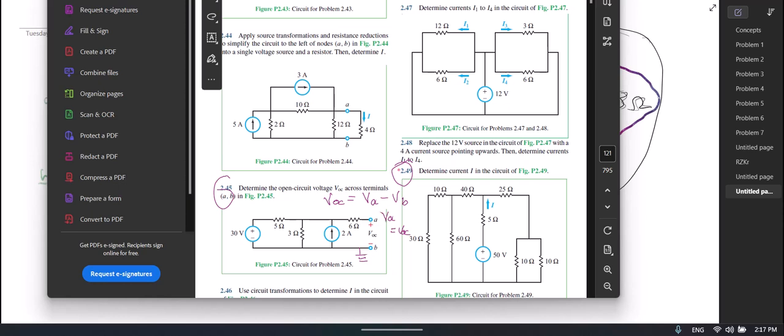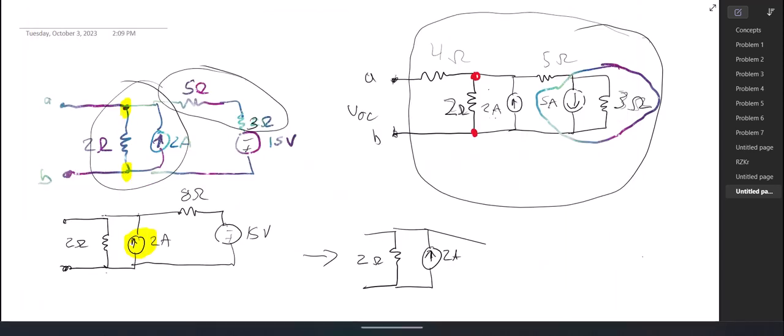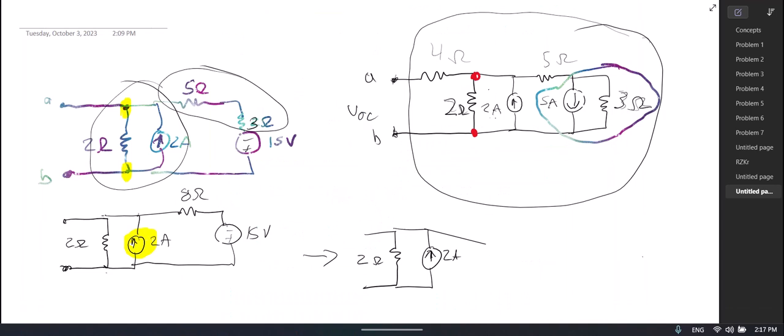Because every element has two sides, and when I talk about the voltage change across it, it could be positive, could be negative, depending on which direction you're going. So that's what those pluses and minuses are saying. And it's not really even saying that A is a higher voltage than B. It's just saying, when I give this number, it's A minus B. That's just how you're measuring it. It could be a negative number. Yep. So that was something that took me a while to grasp and accept.